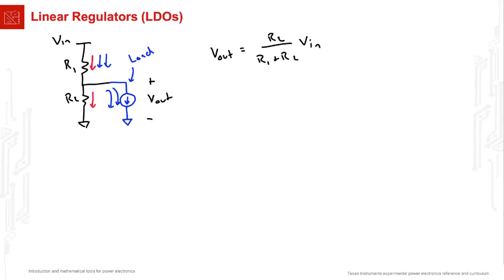Therefore, the voltage drop on R1 will increase, and I expect the output voltage to decrease. So I can demonstrate this in a cartoon as follows. So you can see that with fixed resistors, it's hard to deliver just the right amount of power to a load at just the right voltage, and it's impossible to do so if the load is varying.